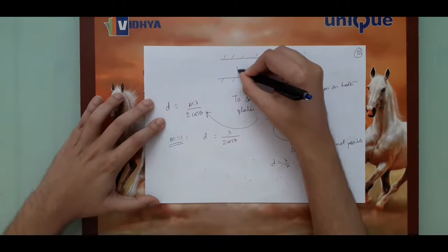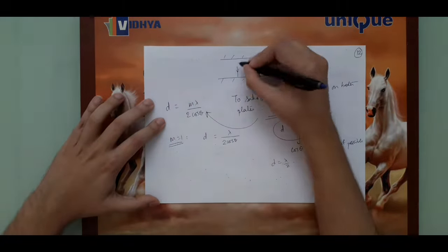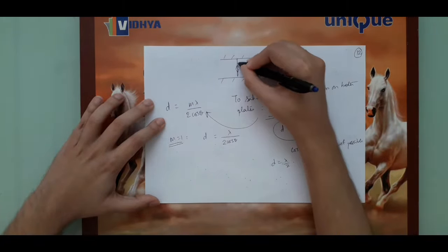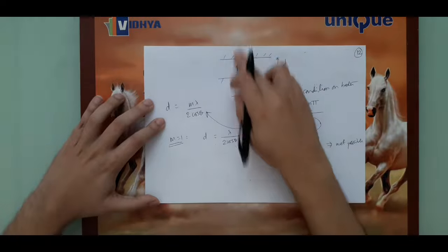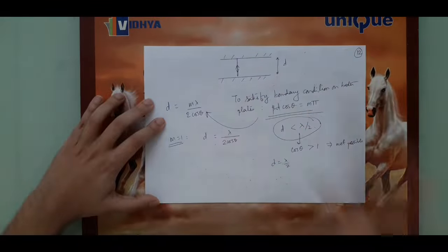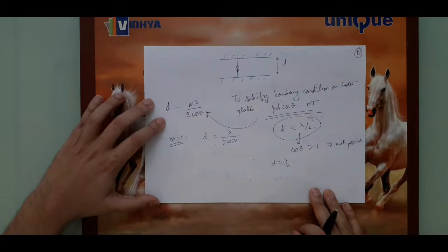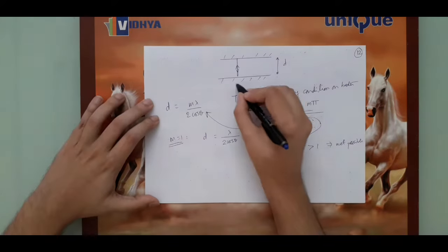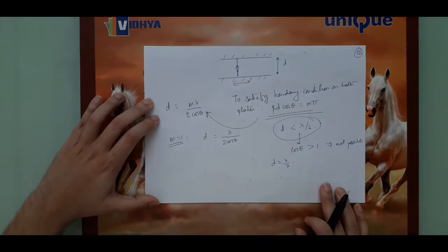That means the wave has to be incident this way. So it's like saying the waves will keep hitting the two plates back and forth, nothing will travel anywhere. So you can very easily prove that the moment theta becomes 0, the propagation constant of the wave this way or this way also becomes 0, because it is a sine theta term.